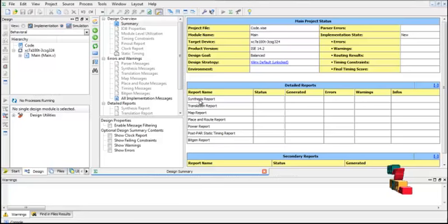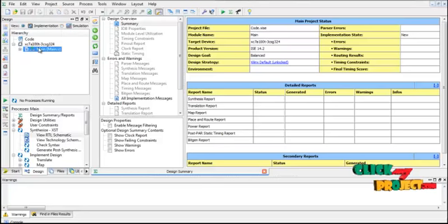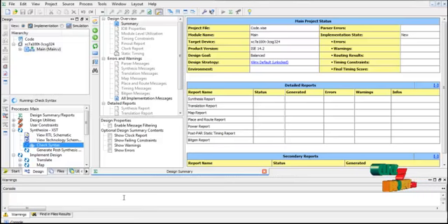Now we are going to discuss the running procedure of our project. In our project we have four steps. First, we check the syntax error; second, we generate the RTL schematic diagram; third, we generate the technology schematic diagram; and finally, we generate the simulation waveform. First we select the implementation, select the main function, then select check syntax. In this process we check the syntax errors of our program. In case of any errors or warnings, they are displayed in our console block. In our program we have no error.